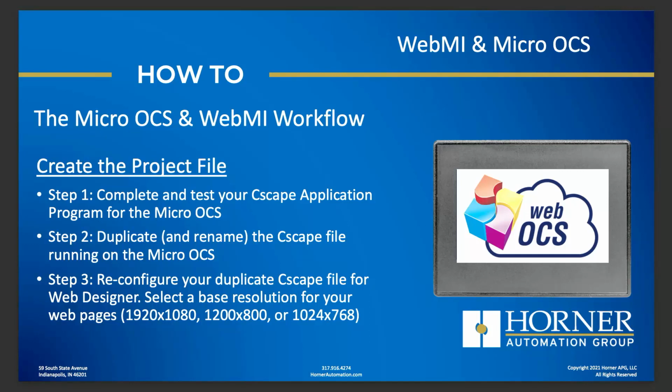Okay, now you open up that duplicate file and you go into the hardware configuration and you change the target from an X4 or an X7 or an X10, whatever the case may be. You change that target to Web Designer. Okay, Web Designer is a special classification in which you have the ability to design web pages for an OCS. And then when you select Web Designer, you also select the base resolution for your web pages. And there's 3 available ranging from 1920 by 1080 down to 1024 by 768.